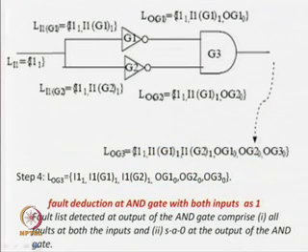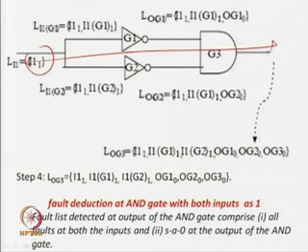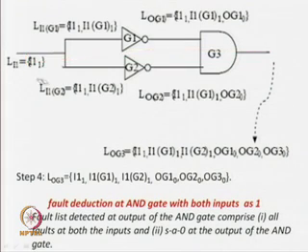So then we started discussing another algorithm, in which we can do the whole thing in one go. That is, we apply one random pattern, and in one scan of the circuit, can we deduce the results about all the faults that can be detected by it? Then we saw that deductive fault simulation was a very good approach for that. We apply one random pattern, and at each net of the circuit we find the fault list that is detectable by that random pattern, and then in one go you can find out which faults are detectable by that pattern.